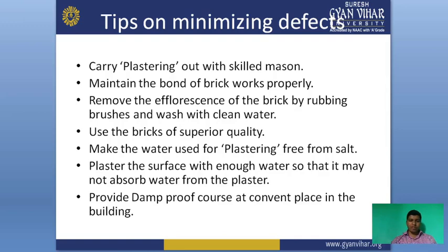While using water in plastering, we have to ensure the water is free from salt. Next, wet the surface with enough water so that it may not absorb water from the plaster, and provide damp proofing at convenient places in the building.